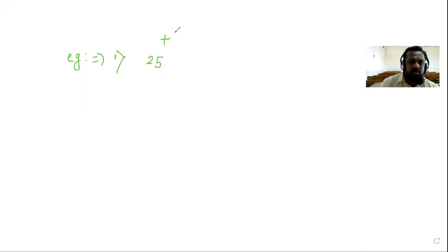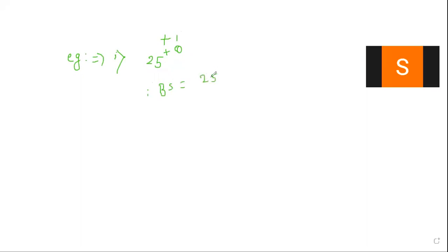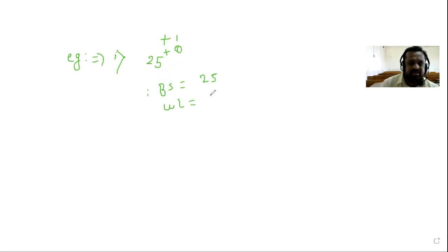25 plus 1, and plus 0. Please tell me what is the basic size here? 25 is the basic size. Then please tell me the upper limit. 26. Yes, 26. Then what is the lower limit here? 25.